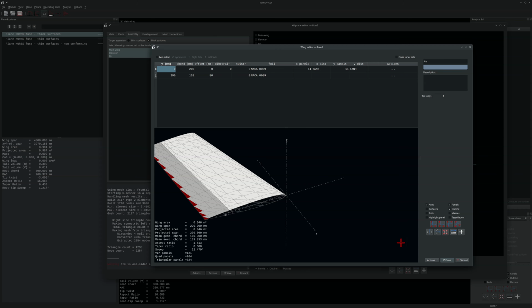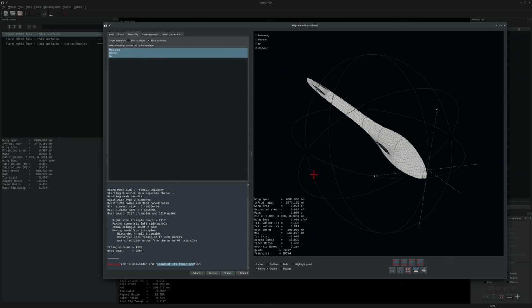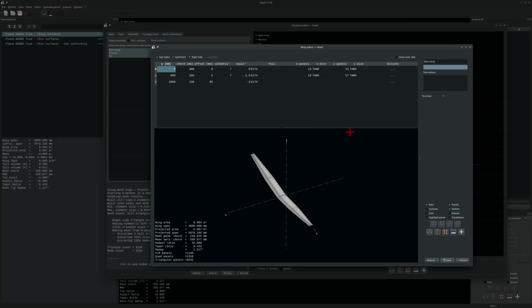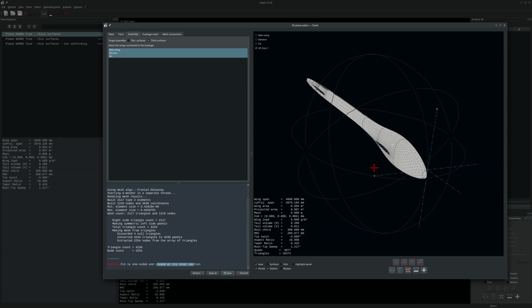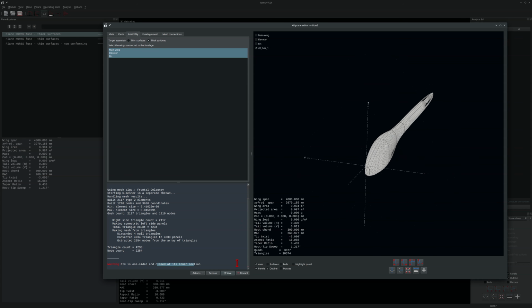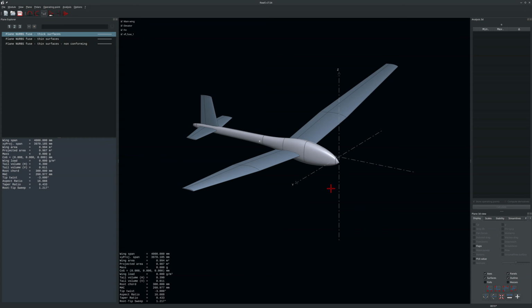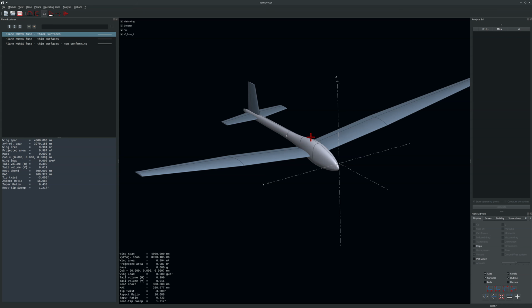In the case of a two-sided wing, well, let's open the editor. Flow5 knows that each half wing closes the other, so to speak, to form one closed volume, so it defaults to deactivating the closed inner side option. And this time our mesh is ready for calculation, and we have our three meshes here.